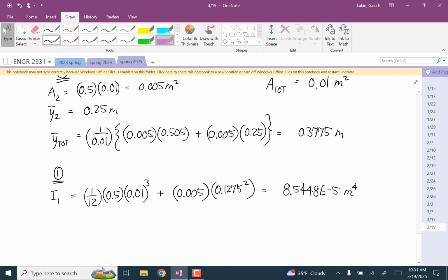So like in an I-beam, the horizontal parts of an I-beam, if you just made the shape, the whole cross section of the beam, the horizontal part, it would bend really easily. Okay, but you take those same shapes and move them away from the neutral axis, you get this big contribution, so that those two short, stubby things actually provide a lot of resistance to bending because you've moved them away from their neutral axis. Does that have to do with like buckling or something?